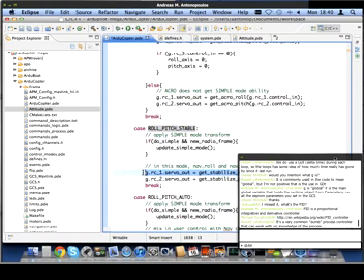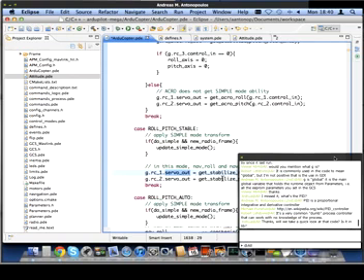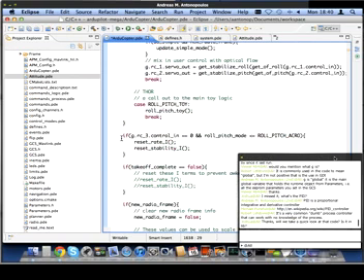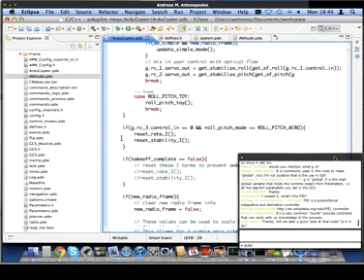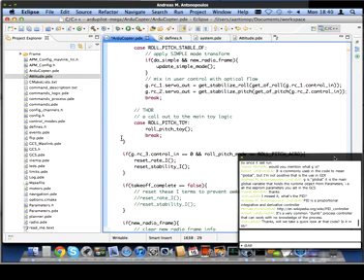Okay, so you can see, right, if you go down just about 6 lines or so, you see this, GRC1 servo out equals get stabilized roll. So, we were just talking about that function a moment ago. It's come back with basically an output that it thinks should go to the motors. We stick that into this GRC1 servo out variable. So that's the thing that needs to get to the motors now.